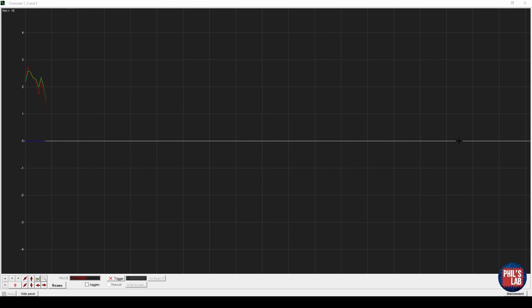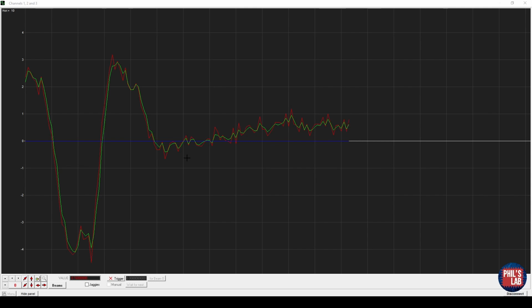So if I start moving it around, I move it below my initial level, you can see these are a much closer match, and we've attenuated some of the high frequency noise. So this seems like a fairly good compromise. But remember, this depends entirely on your situation. Sometimes a very slow rise time or very heavily filtered signal is preferable to something like this. But with our low-pass filter being tested and it working, let's go over to altitude estimation.